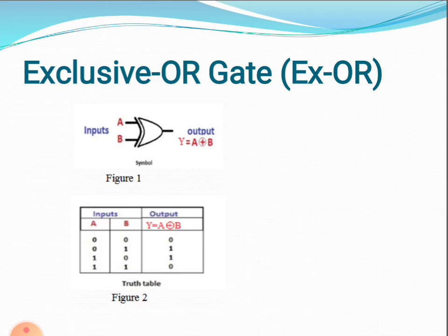If we compare the truth table of the XOR gate with that of an OR gate given in the OR gate truth table, we find that the first 3 rows are the same in both, only the 4th row is different. This circuit finds application where two digital signals are to be compared.